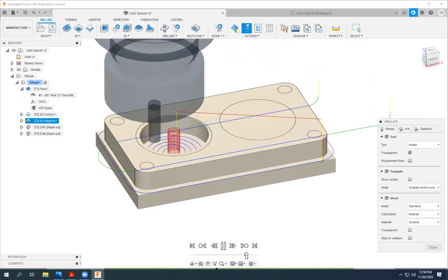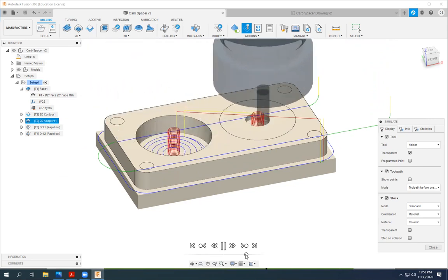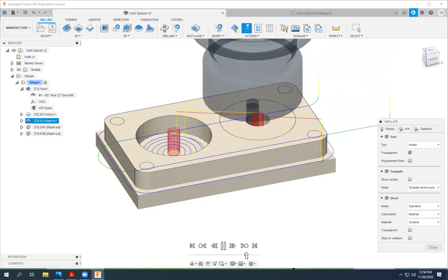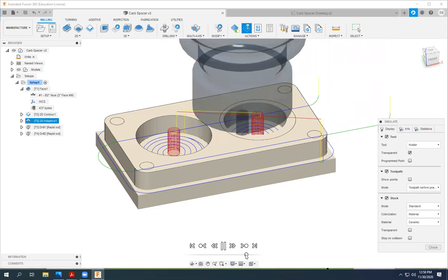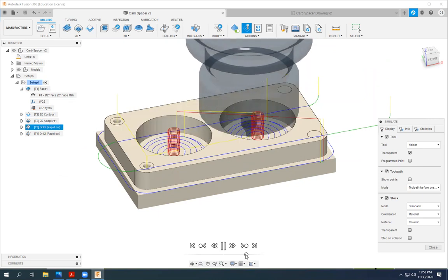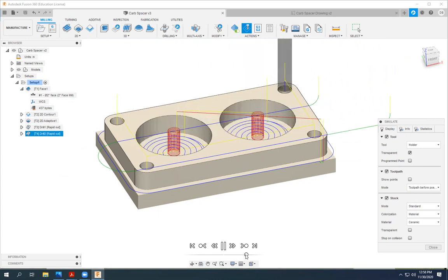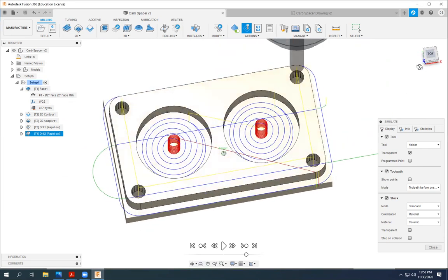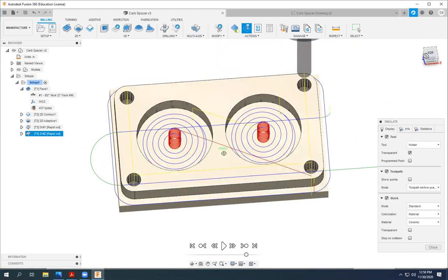We can speed that up a little bit, get through it more quickly. And one thing to note is that the spindle on a CNC mill doesn't actually move left to right. Comes the drills. And now we're done. All right, so again, we've got some chatter, we've got some finish issues, but the thing is, we were able to create our entire tooling operation, all the tool paths to be able to mill that part for our finished operation. Okay, so that's the whole point there.